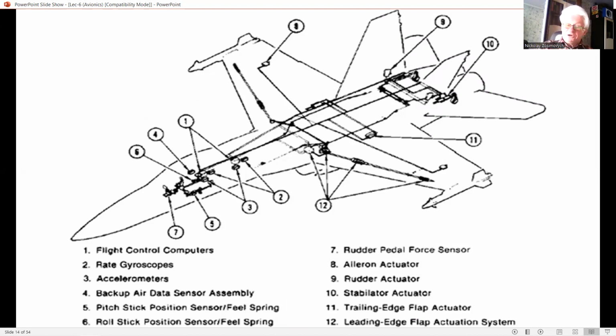And second, aerodynamically, through the changes in the aerodynamic pressure distribution over the control surface and adjacent surfaces when the control surface is deflected from its datum position. These forces are proportional to the deflection of the control surface and the dynamic pressure.